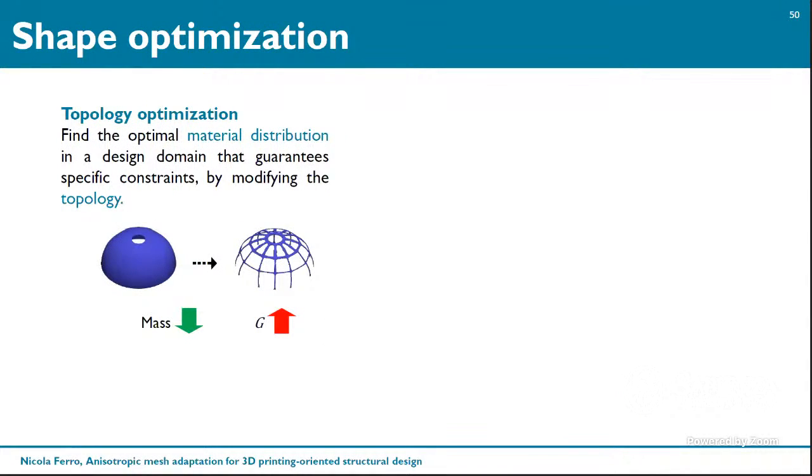Basically, what we saw is that topology optimization works in reducing the volume that we are considering. So we can design lightweight structures, but at the same time, if we compare the mechanical performances of interest between the full material configuration and the reduced material one, we can have a deterioration of the mechanical properties that one can be interested in. For example, if we consider the compliance, it is straightforward to understand that the compliance of the full structure is less than the one associated with the reduced one.